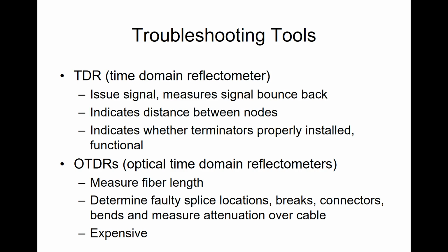We also have a tool called a TDR, Time Domain Reflectometer. This actually sends a signal, and as it bounces back, it reads that signal, and it can tell you if it's connected right. At its basic level, it can tell you how long that cable is, and it can check all the way along through it. We also have one called OTDRs. And when we do fiber, we look at OTDRs.